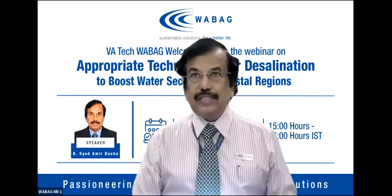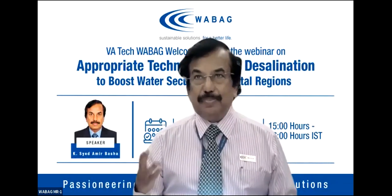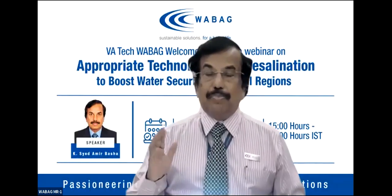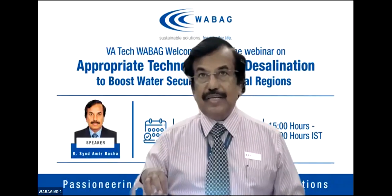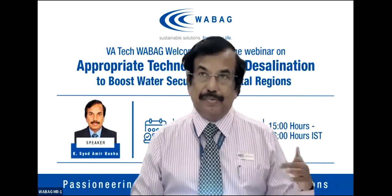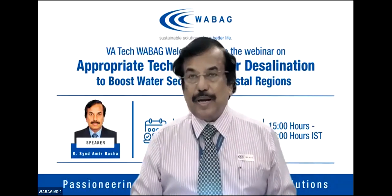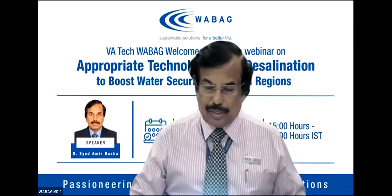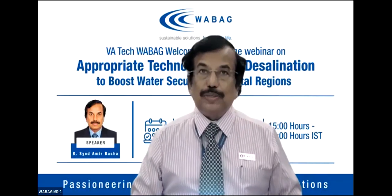I can say that a brackish water plant can be installed in order to treat this water and produce drinking water. We can go up to 75 to 85% recovery depending upon the chemical constituents in this water. Brine disposal can be done either by means of an evaporation pond or by injecting into deep wells. Or if there is any seashore nearby, we can dispose it there. But since you are talking about Delhi, you have to have an evaporation pond. In Saudi Arabia, there are evaporation ponds for plants up to 120 MLD in order to dispose the brine.